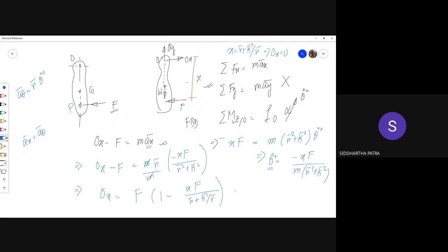But the horizontal reaction at the pivot point becomes 0. Now this is an important result. Whenever a batsman in either cricket or baseball is hitting a ball with the bat, or in any other game, when they are trying to hit a ball with a racket or a bat, if they want the object to go furthest with very little effort from the wrist, they would try to hit the object with the center of percussion.